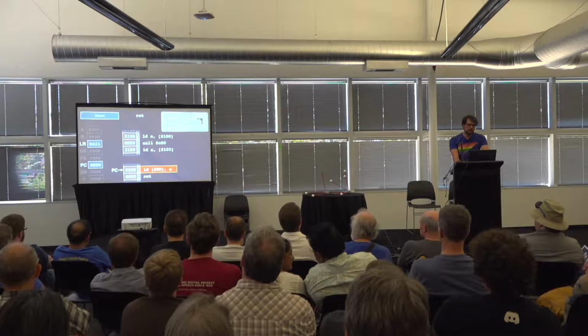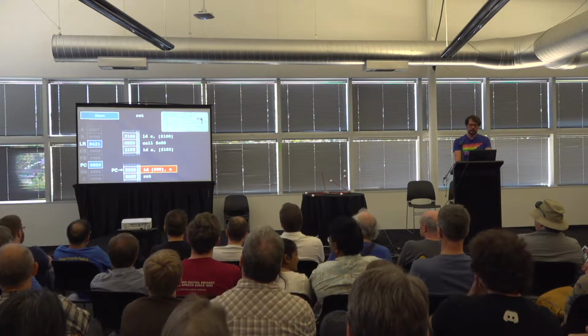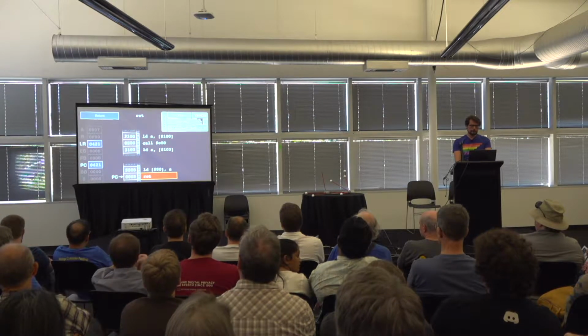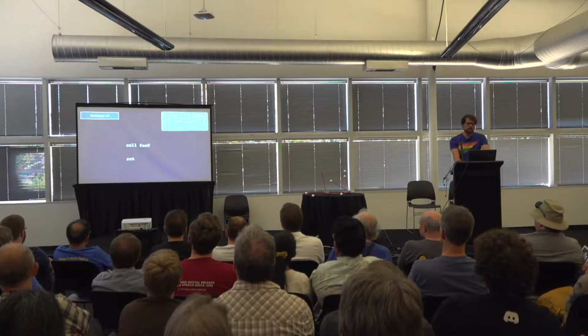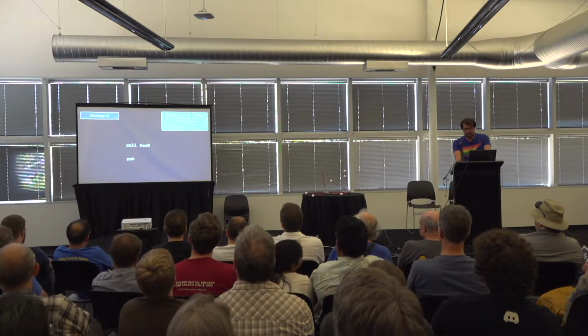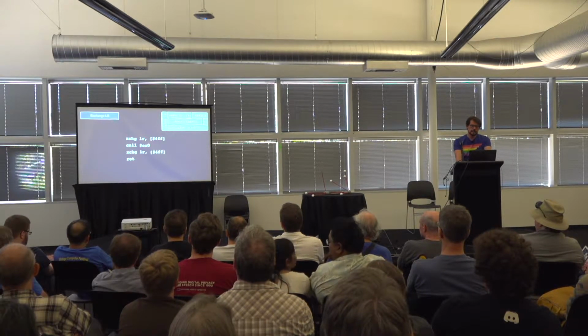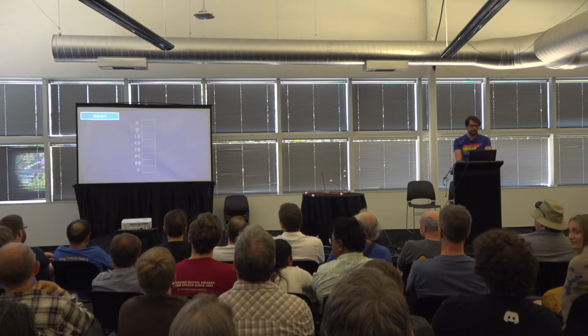At the end of a subroutine, the ret instruction effectively copies the contents of the link register into the program counter, so execution resumes just after the call instruction. If the subroutine wants to call its own subroutine, the program has to save the link register before and restore it afterwards. There's an exchange instruction specifically for this. For additional levels, a stack can be constructed using the indexing syntax.